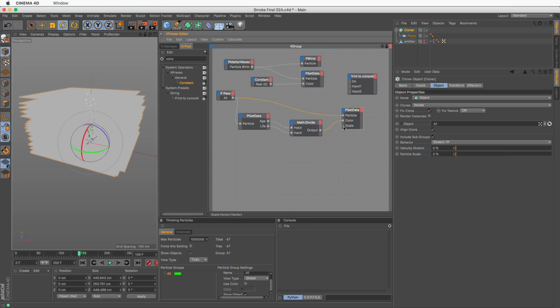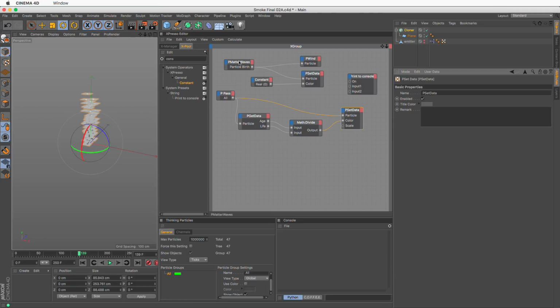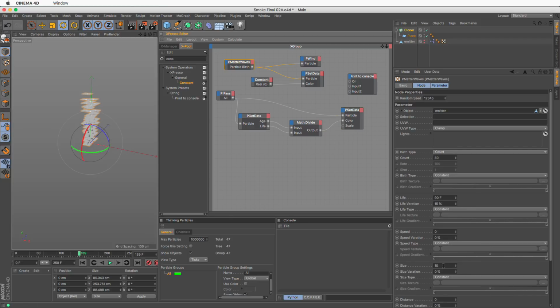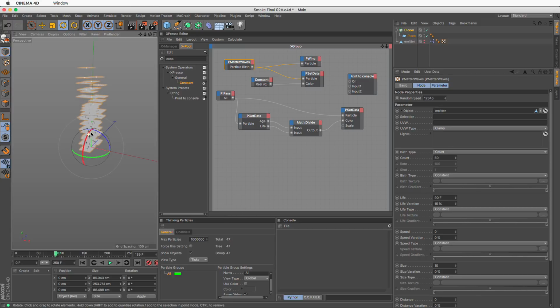I'm going to leave this open for now, and I'm going to go to the particle scale and do this. By default, when we generate an object, it has a size which is 10 and all that. And I think if I make this 100, now they're going to be in their actual size. I'm going to leave this default. Don't worry about it. We are just going to play around with the scale and some range mappers to control the size of our placards.